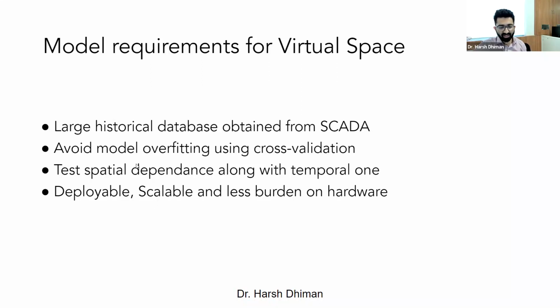So let's say if you're collecting data of a gearbox, you can also collect data for the generator because it is spatially close to your gearbox. So generator operation can affect gearbox operation. So if your model is data dependent, you can always go ahead with spatial data as well. Then deployable, scalable, and less burden on hardware.